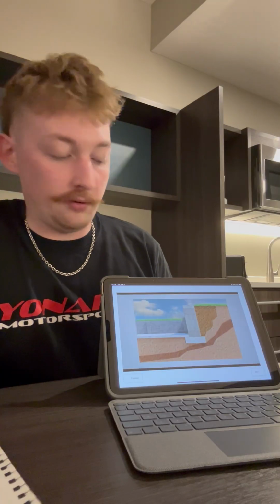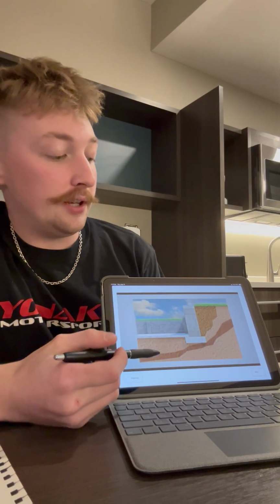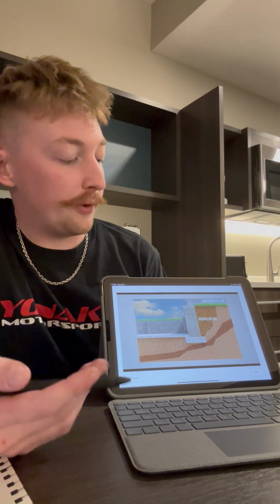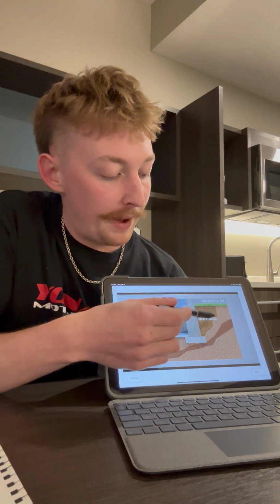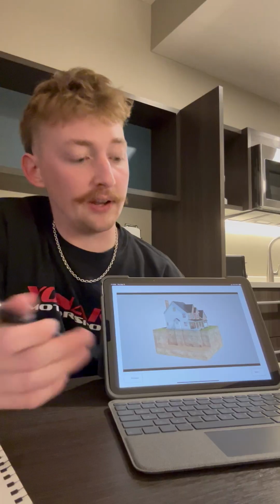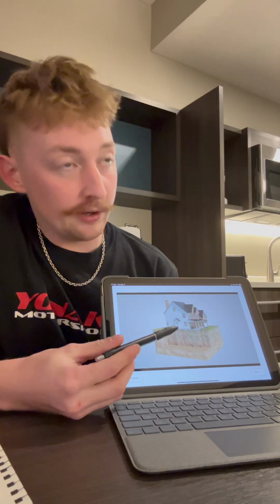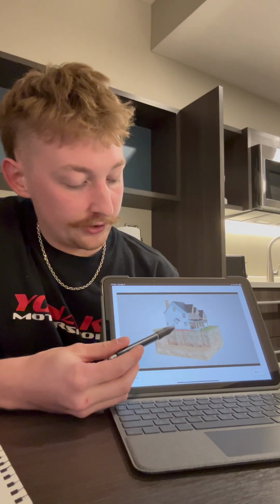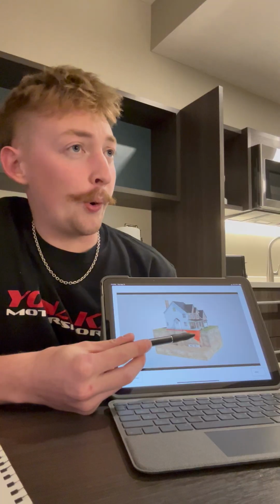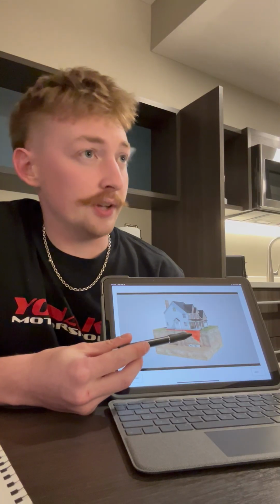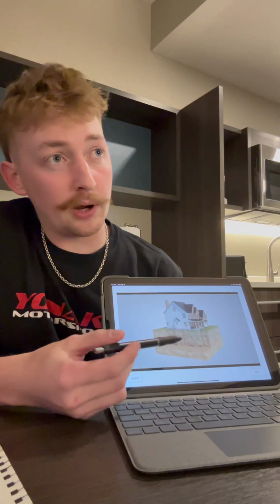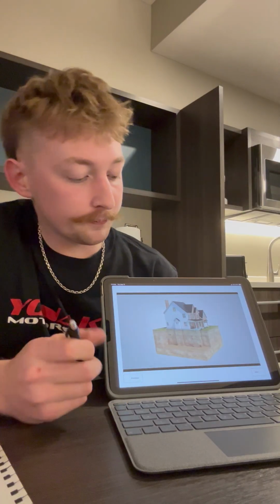So, obviously, when they dig out the hole to build the foundation, they're going to fill it in with backfilled soil. This is like active soil, and you have your native soil underneath, hasn't been touched. This is a different part of the active soil here that's shown. So this is soil that's prone to moving and usually does move pretty much most of the time. So this is what we have to worry about. It's probably what's causing the issues here.